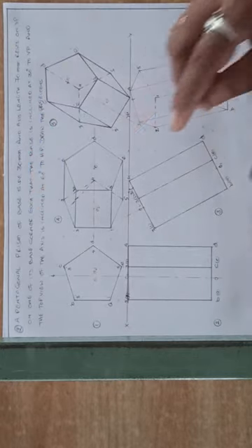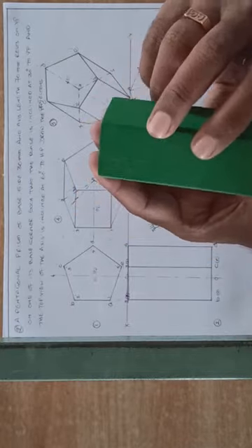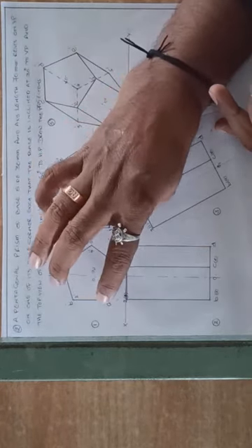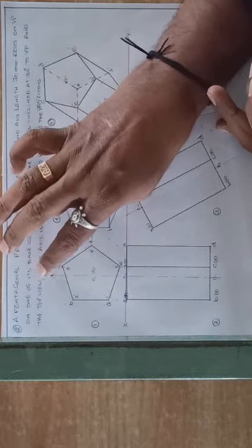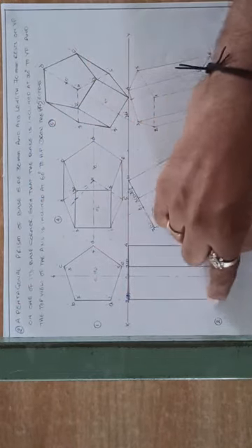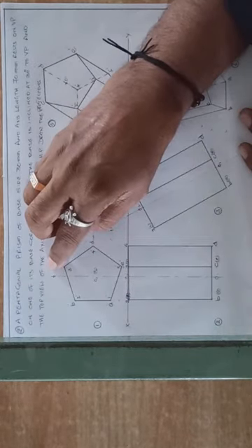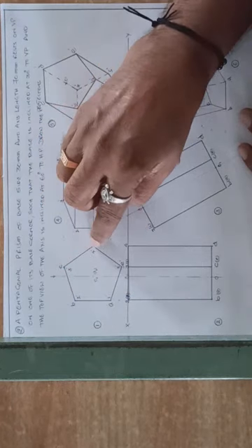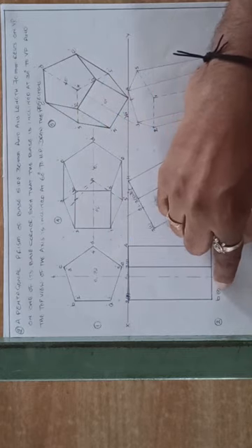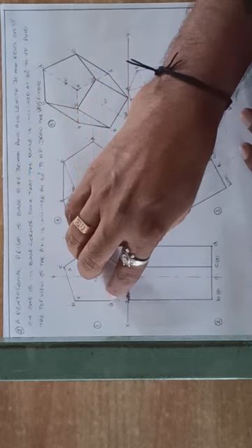That is resting on an edge before, now it is resting on a corner. So in this position, draw the true shape in the front view. Mark the notations, already you know it, A, B, C, D, E, 1, 2, 3, 4, 5, and then project the lines downwards. So what is the length given? 70 mm. For 70 mm, close the box. So mark the notations, looking from the top: A visible, B visible, C visible, D visible, E not visible, A not visible. E is in bracket, A is also in bracket. Similarly, 2 visible, 3 visible, 4 visible, 5 not visible, 1 not visible.